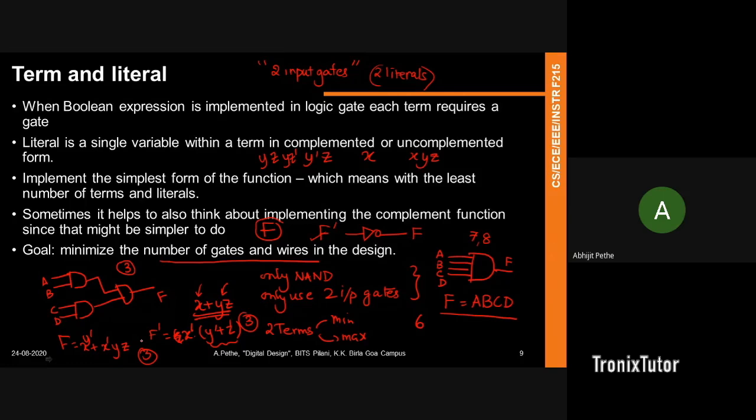What you want to remember is that it is going to tell you how many of those inputs are actually valid, right? Suppose you want to reduce the number of inputs which are essential for you. All you're doing here is removing the unessential stuff in your expression. So you want to get to the basic minimum number of terms which are needed to implement your gate. All you have to do is ensure that the number of literals is less, the number of terms is less, right? Keep going down till you know you cannot go lower than this.